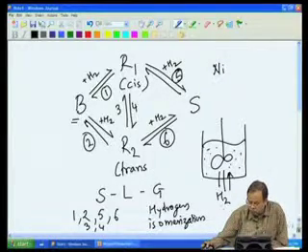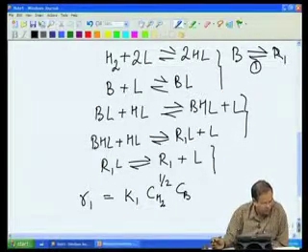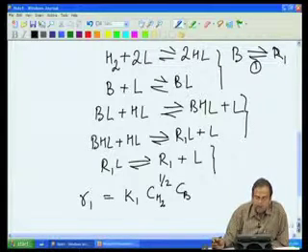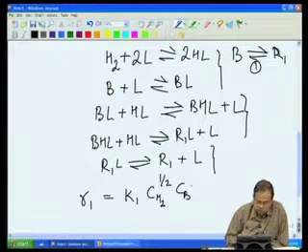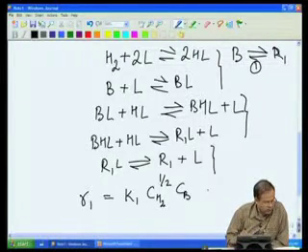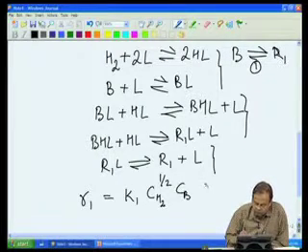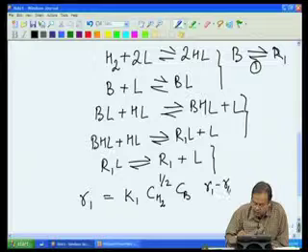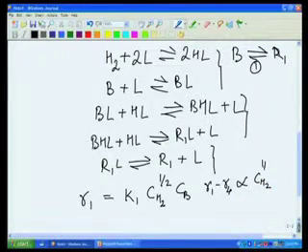So, what we just wrote was the typical mechanism for hydrogenation reaction, and we get this kind of rate laws. In fact, rate laws for all the 4 reactions R1 to R4 are of the same form, namely these rates being proportional to concentration of hydrogen raised to half and corresponding substrate reactant.